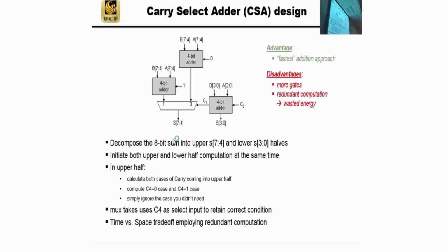Then what's the output that's going to go into T1? What does this box do? It chooses. It's a decision box. It's an if. How do you choose one or the other? It depends on C4. If C4 comes as 0, then you would choose the one on the right. So what we're doing here is using the output to select in a multiplexer to choose one.